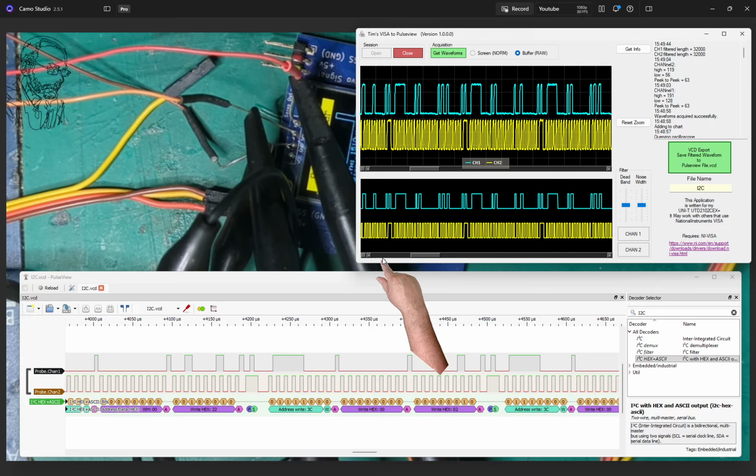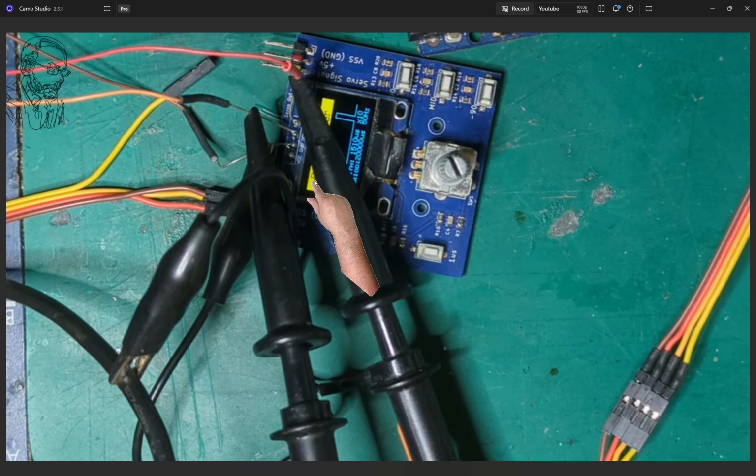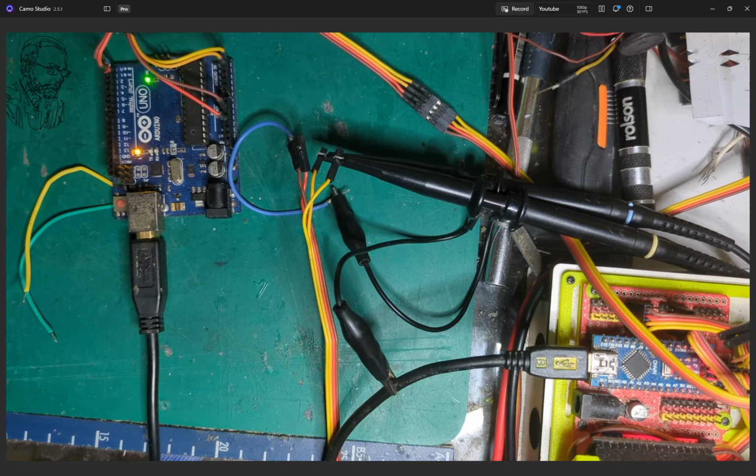What I wanted to do is this, and then I wanted to show you I2C communicating from one Arduino to another. So if we go back to here, let me just set up what we've got. Alright, so what I've done now is I've connected it to the I2C bus here. We've got the ground, the VCC, the data, and the clock wire here. This wire is actually the same, connected to the same wires here.